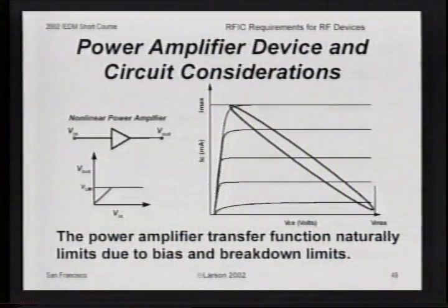Even going from 3% efficiency to 6% efficiency is a huge breakthrough in many of these technologies. So the power amplifier is sort of unique from that perspective. The level of integration is less important than getting that extra little bit of efficiency. And the problem is not only that they break down, but their performance also tends to saturate or limit, as we saw earlier.